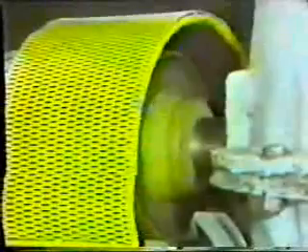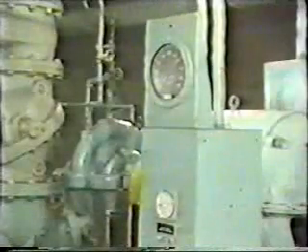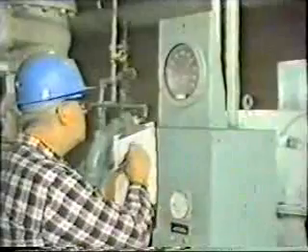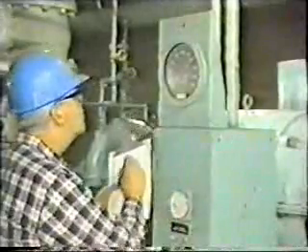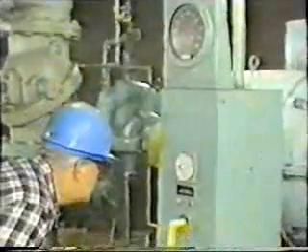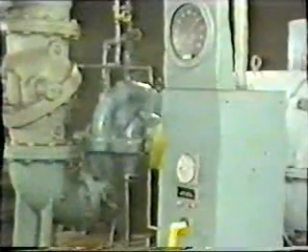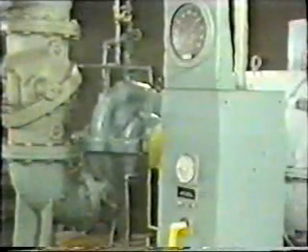Once you finish questioning the operator, you need to check other sources of information. As a troubleshooter, whenever possible, perform an operational check of the pump so you'll know firsthand exactly what the symptoms are. You may find clues about the cause of many problems in the indications on the gauges and recorders. Our gauges indicate that discharge pressure and running current are normal.